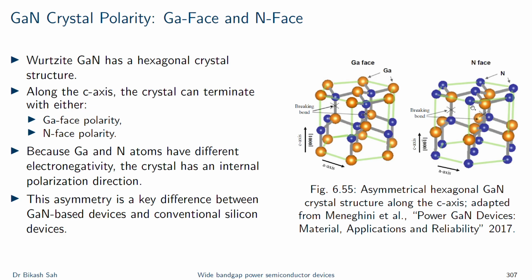Because in GaN, the direction of the polarization is tied to the crystal orientation. Gallium and nitrogen have different electronegativity, and the bonds are not electrically symmetric. In a centrosymmetric crystal, internal dipoles would cancel perfectly, but in wurtzite, that is GaN, they do not cancel in the same way. In this figure, you can visualize that the atomic arrangement has some sort of directionality. The directionality later determines whether the polarization charges appear in the AlGaN or maybe just the GaN stack, and whether electrons accumulate at the interface.